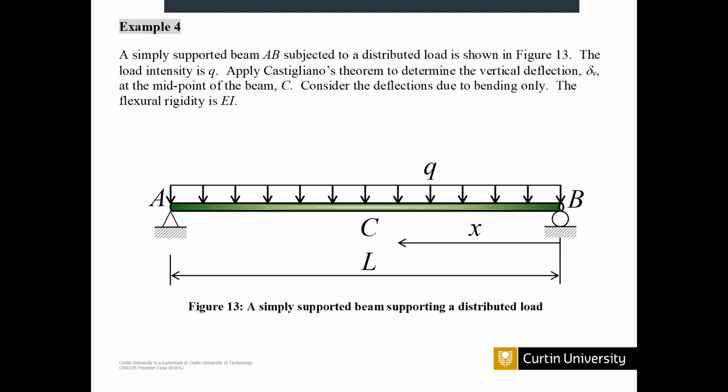Sir, do we always make the dummy load equal to 0 after integrating? Not after integrating, after differentiation, sorry. Yeah, after differentiation? Yes, of course. Is that the case every time? Yes, the dummy load is not an actual thing. You are just using it to find the differential equation, I mean the first derivative, using that one. So Q doesn't have a value. It doesn't have a value. Yeah. Okay, sir.